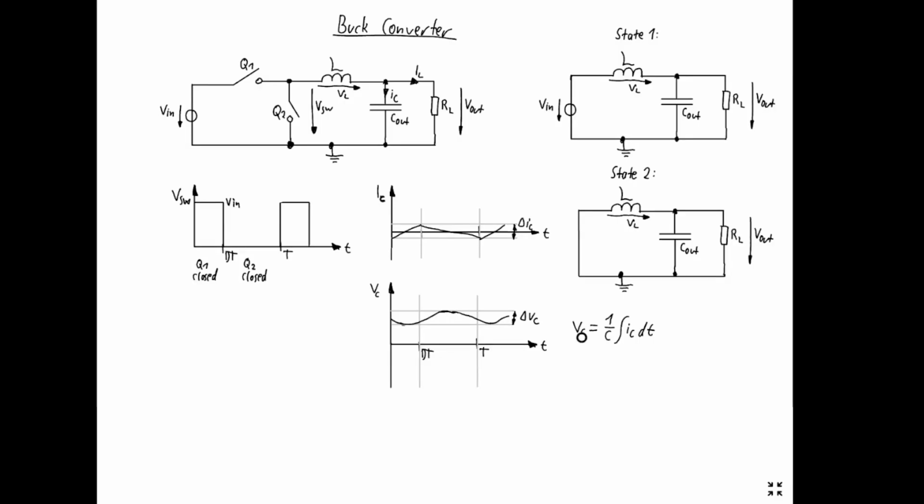Now we as well want to get a formula to size our capacitor. Like before, we could calculate the integral for one sector from 0 to dt, for example. Or we simplify it and just calculate the triangle area here, because this gives us the whole voltage ripple. So we apply this formula and just calculate the triangle. And this now can be used to size our capacitor.